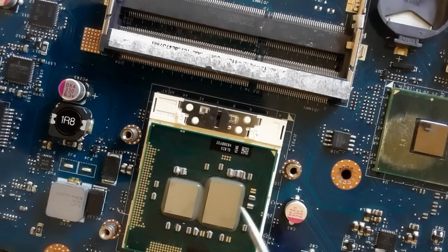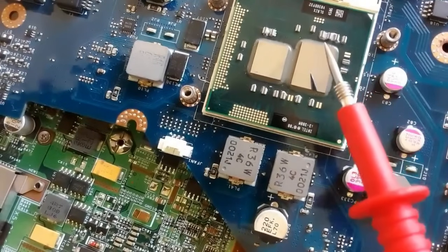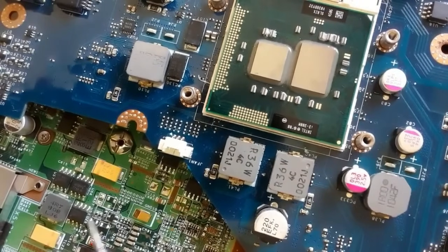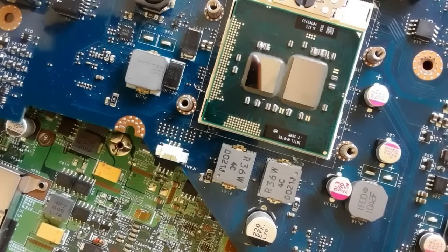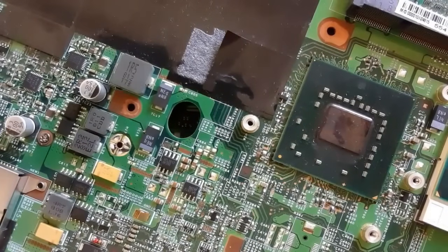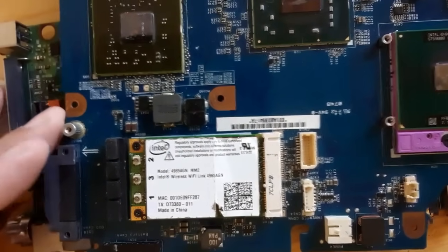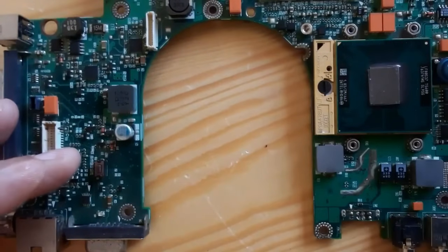In modern laptops, you will find the graphic card or the GMCH integrated with the processor in just one chip. But for the old motherboards, you will find all chips are separated. For example, you will find the processor, the GMCH, and the graphic card separated. And of course, in some improved and modern motherboards, you will find that the processor, the GMCH, the graphic card, and the ICH are integrated in just one chip.